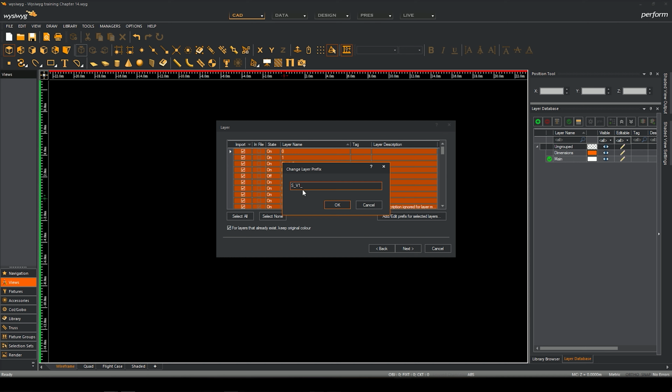And if I need to update my CAD plan and re-import it, I can do it as stage underscore version 2, and I can turn off all of V1 but leave them there. So it'd be really easy for me to flip between different versions, which makes it easy to see what's changed. I can even set V1 to be like a light grey colour and V2 to be a white, so you can see the greyed out version underneath the white version.